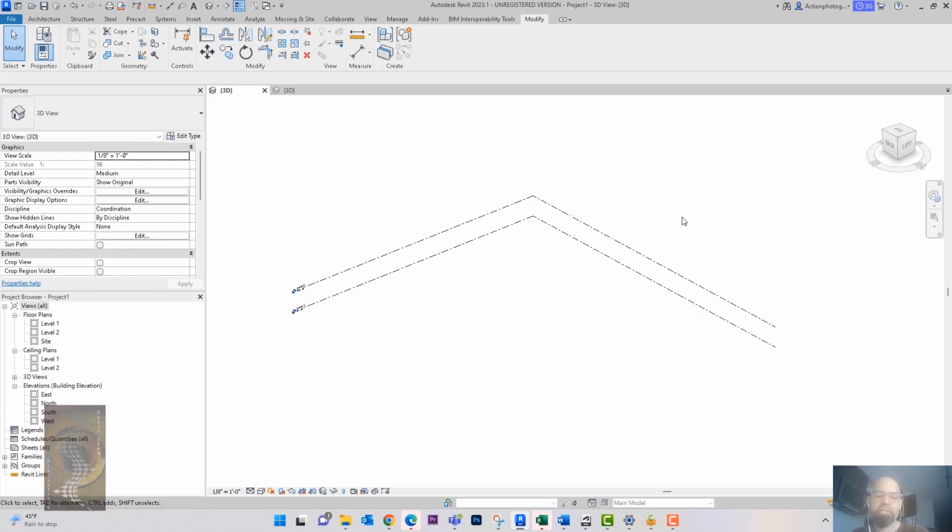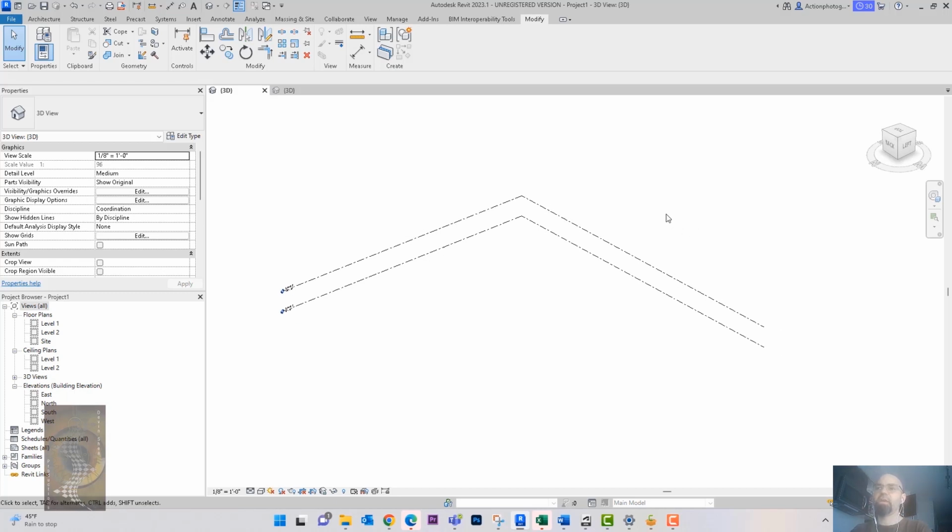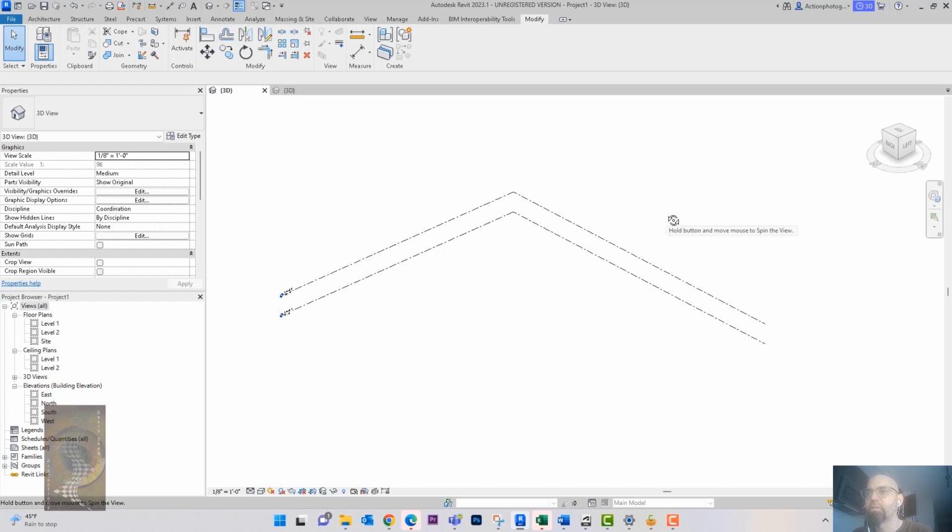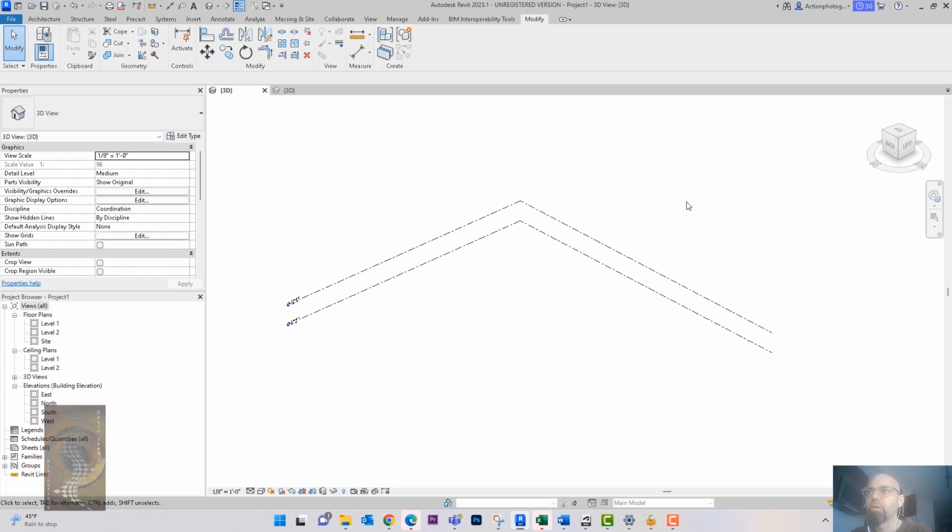What these are is point-driven geometry, and they're literally the only thing in Revit that allows you to manipulate them in 3 dimensions. Like in any of your basic 3D modeling packages like 3ds Max, you can create a 3D mass and then grab the edges or vertexes and pull them around to create 3D shapes. But as we all know, Revit is very limited in its abilities to create 3D objects.